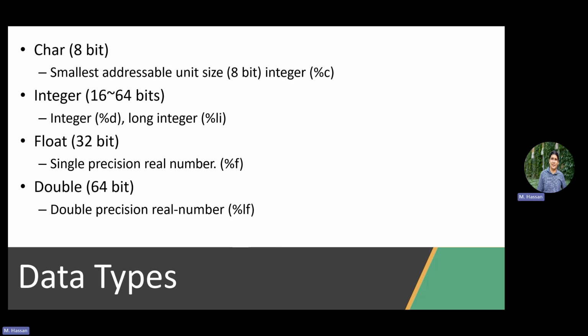Good. So why is it good to know these things? Because, for example, in the C standard, the width of an integer is in fact defined by the machine width. So if you define something like int x and you put in a number and try to execute this on an ESP32 or an Arduino or on our ST device, you will have a different width, because the integer is variable based on the machine. People in embedded systems, and again, we'll see in the next lecture, the standard for safety critical systems, what we call MISRA C, forces you not to use a variable integer width. You must put the width in the type. Why? To be deterministic, to be independent of the target machine. You have to tell me you're using an int8 or an int16 or an int32 to make sure that your software always has a deterministic behavior. Okay?